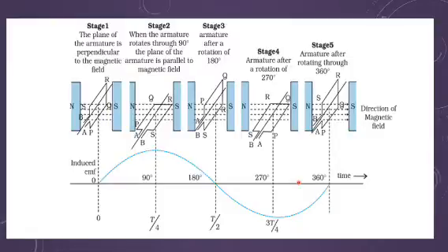I have to make a complete circle. So when I'm completing the circle, the current is getting changed, or I can say the induced EMF I'm getting is in this form, that is the sinusoidal form. It means it is changing after every half cycle, and this is termed as your alternating current and induced EMF, or I, whatever graph you go with. So this is with the change in angle or with the change in time.